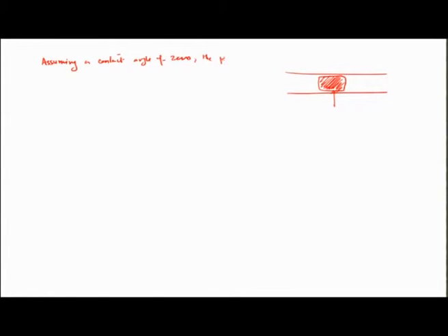So, the pressure inside the bubble is estimated through standard equations for delta P in this kind of situation. Delta P is twice sigma by R, sigma being the surface tension of the liquid water bubble interface.